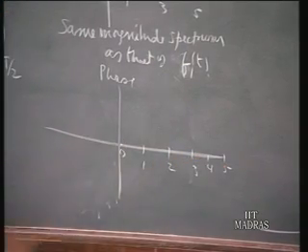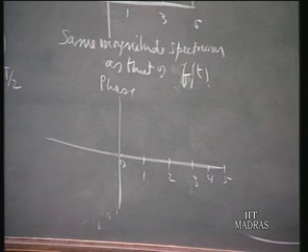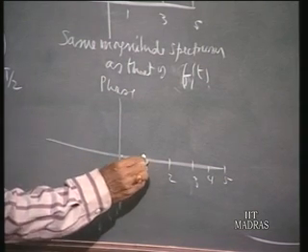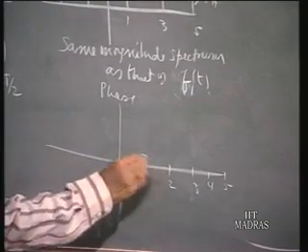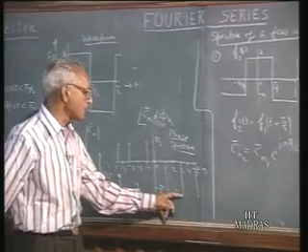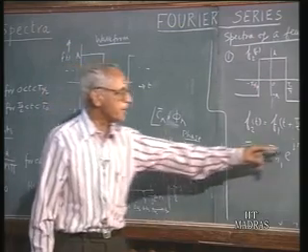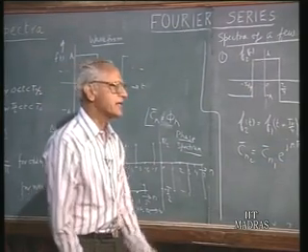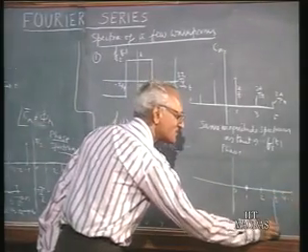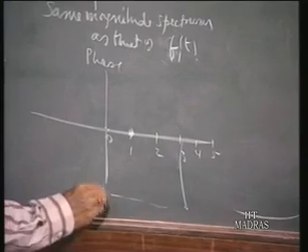DC, of course, there is nothing. At 1, it is minus pi upon 2. So, add to that another pi upon 2. So, this becomes 0. At 2, there is no component to deal with. At 3, it is minus pi upon 2, to that you add 3 pi upon 2. So that becomes 180 degrees. You can as well say it is minus pi, plus pi or minus pi are one and the same.